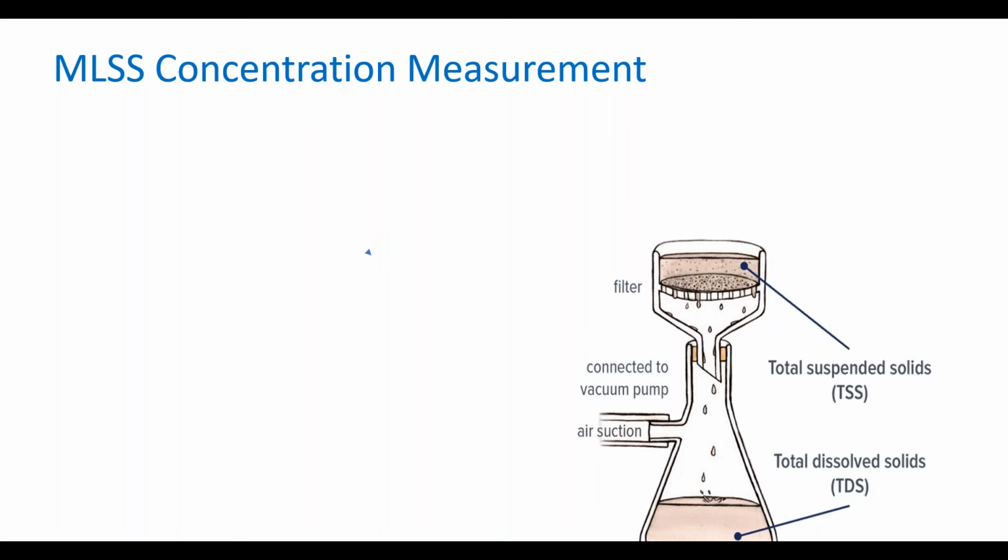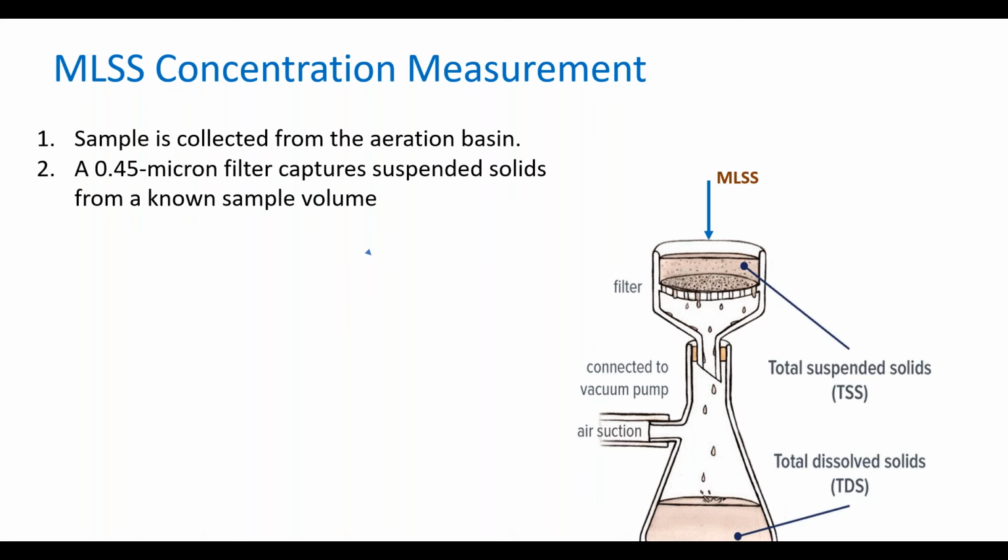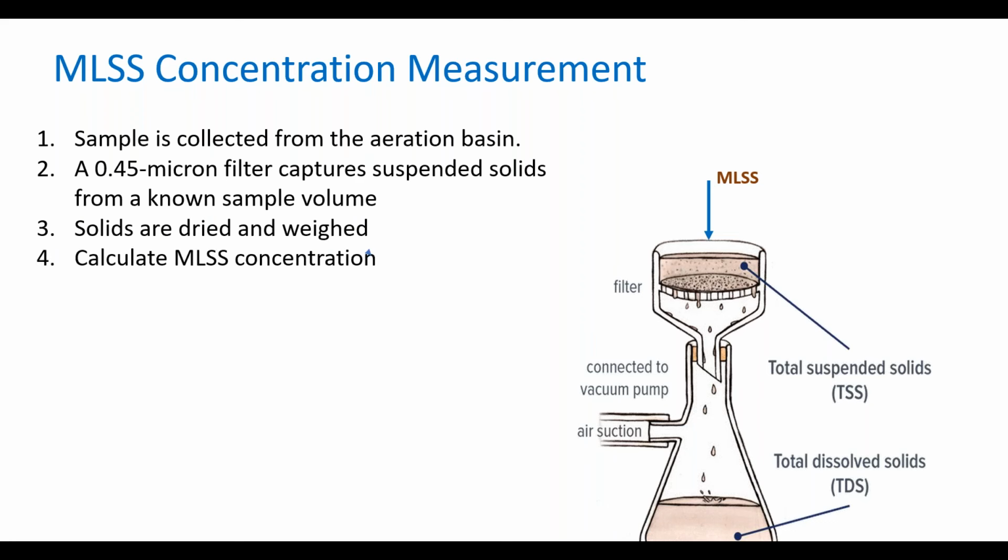You take a sample from the end of the aeration tank, and you filter it through a 0.45 micron filter that captures the suspended solids. And then you dry the solids and weigh them, okay? And then you calculate the MLSS concentration.